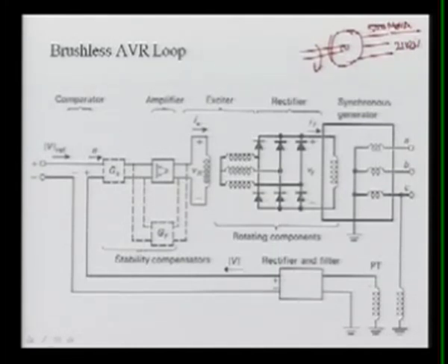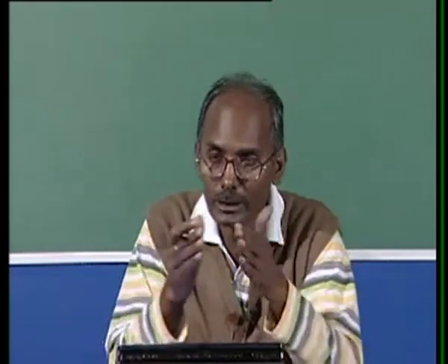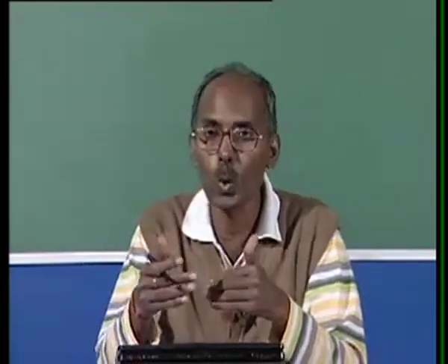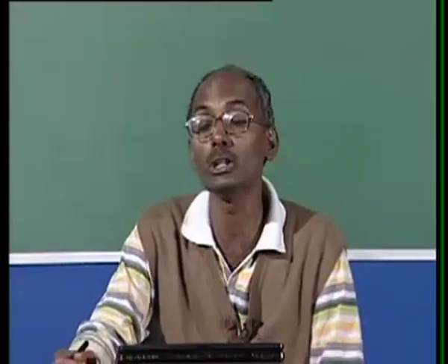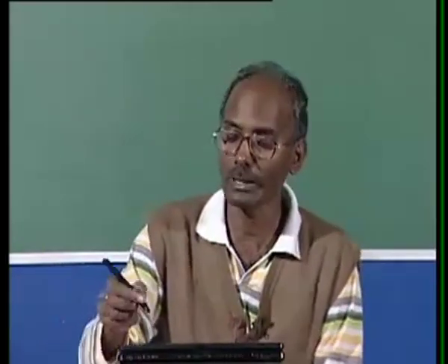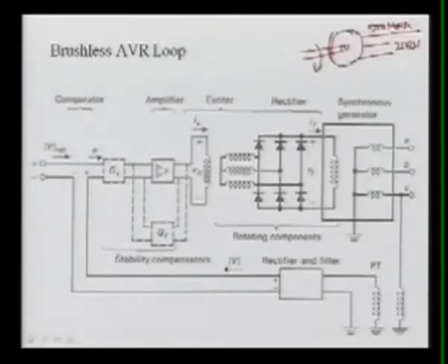On the stator, once it is static, we can provide good insulation between the windings, the core, and the yoke. All of it is very easy, and it is also very easy to cool. So in synchronous generators we always put the armature winding on the stator and the field winding on the rotor.